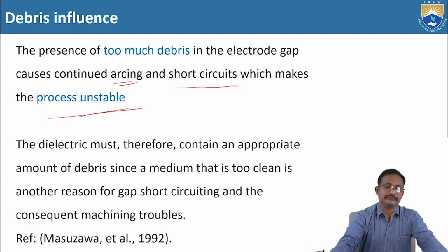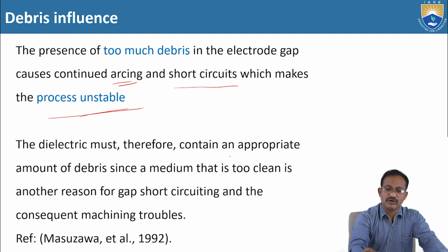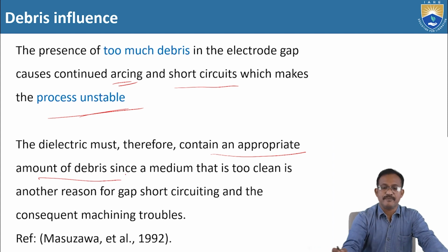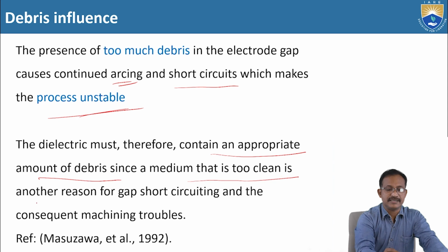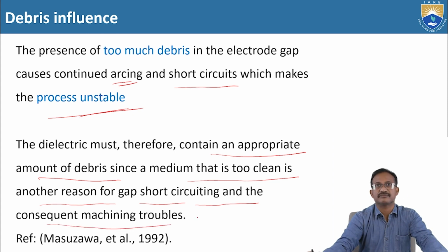The dielectric must therefore contain an appropriate amount of debris, since a medium that is too clean is another reason for gap short circuiting and the consequent machining troubles. Already we have discussed this. If the debris is too much, then what will happen?